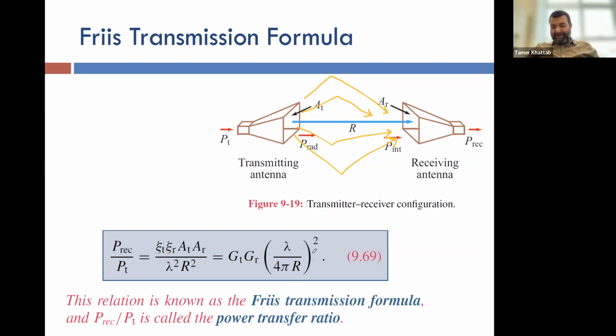Free space will almost always do better, with less loss, compared to multipath. And practically, to accommodate for those multipath effects in path loss analysis, rather than this being to the power 2, it becomes to the power 2.1, 2.3, 2.5, 3, 3.1, depending on the environment.